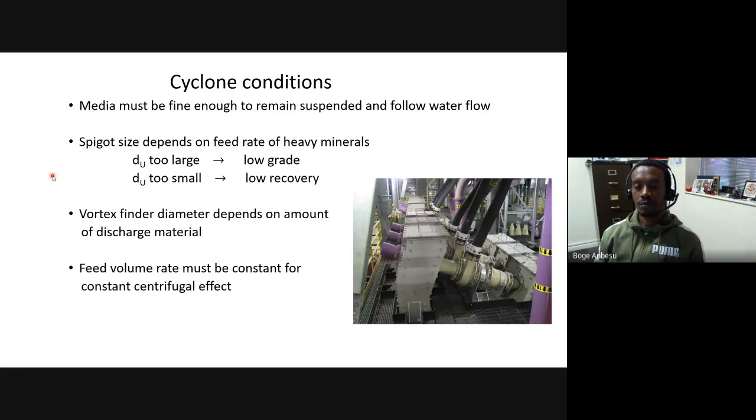Because I said, if we make particles from magnetite, and the magnetite is used to make up a media, and then you're processing a lithium ore with this kind of media, what you don't want is the magnetite to actually separate itself in the separator. Okay, because the magnetite should remain suspended, and that should be helping you as a media rather than separating itself out from the media.